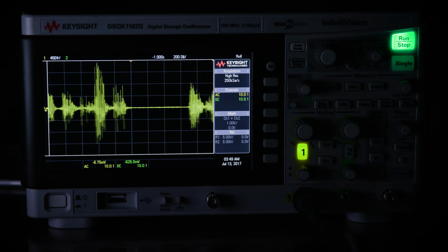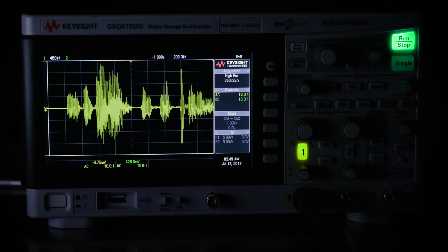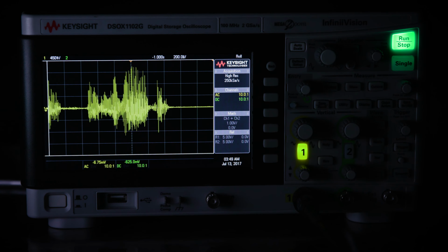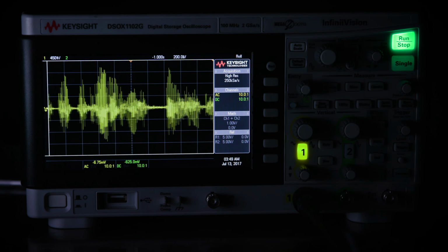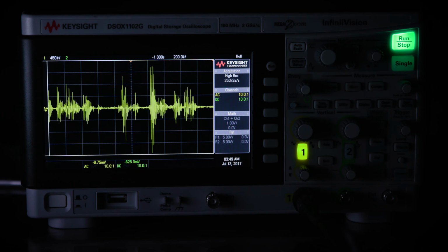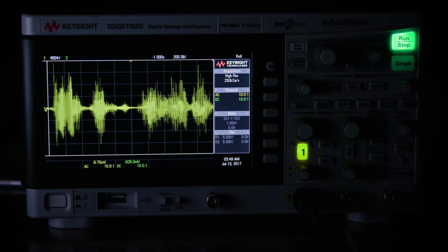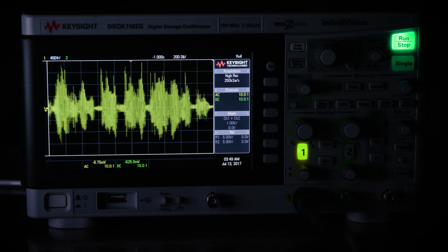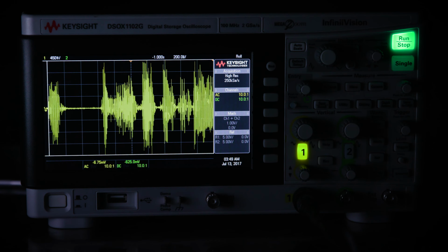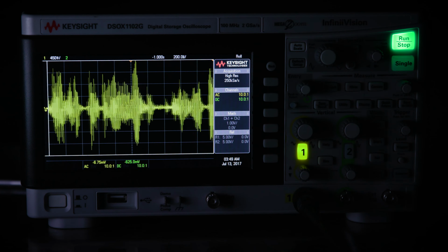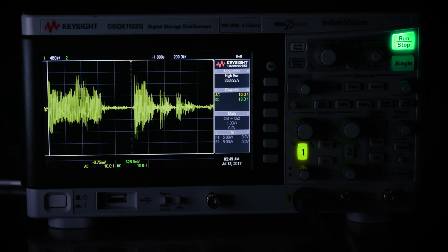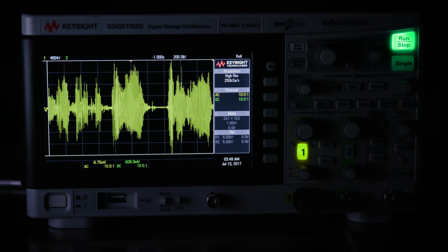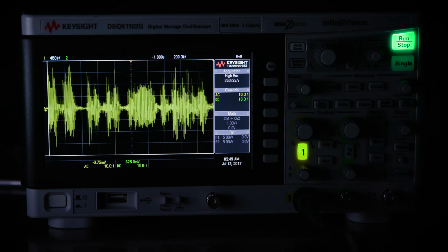I know you can actually plot out the noise floor based on the x-axis of sample rate, and as you start to interleave, you see the entire noise floor go up a little bit just naturally. Part of that is you're increasing the bandwidth of the system when you do that. The other half is if you don't have this offset calibration, because if you take every other sample and move it up and down a little bit, it'll look like noise. But mostly we should hopefully calibrate almost all of that out. So what you're seeing is more bandwidth is more noise. Twice the bandwidth is going to give you 40% more noise.